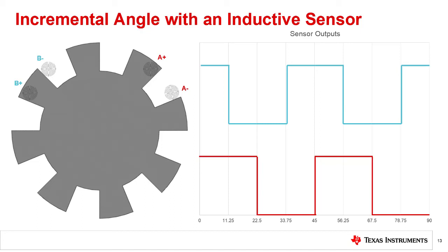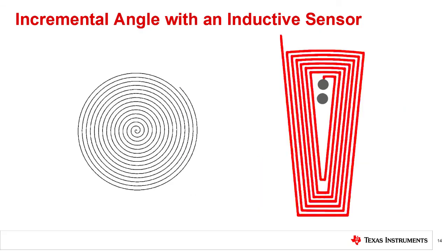Discrete angular position is then easily determined by tracking the edge transitions combined with the direction information. If a counter is incremented at edge transitions during clockwise steps and decremented during counterclockwise steps, we can easily track the approximate angular position of the object.